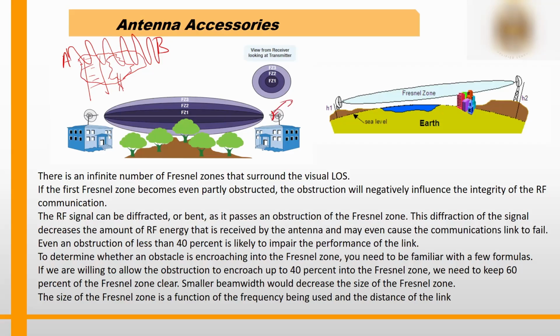So there is something called RSSI, right? And also the signal has to hit the right aperture of the antenna. Then only the signal will be understood as ones and zeros. Okay. If 100% of the radiation is received at the end receiver, then it's a very good signal. But ideally, that's not possible. Okay. Either because of the free space path loss or through some interference like this, some part of the radiation will be gone.